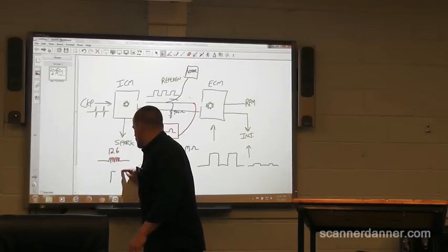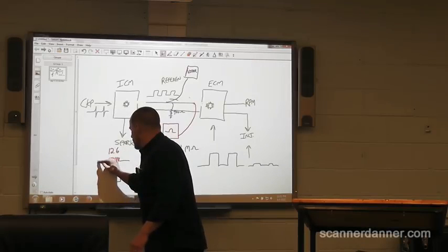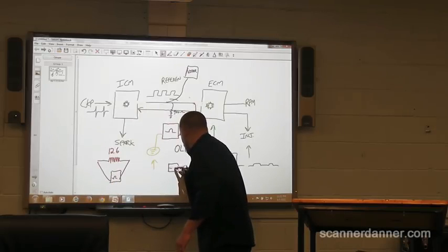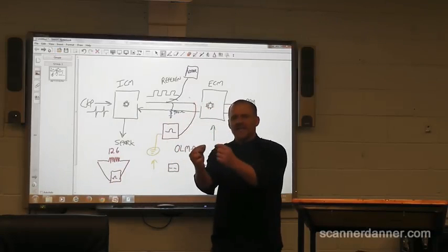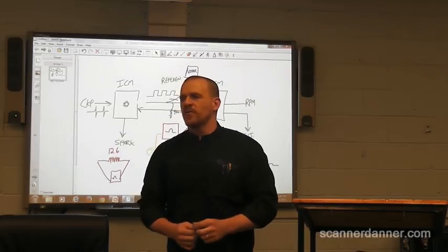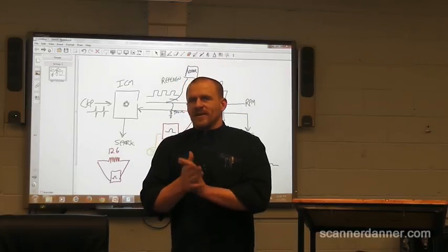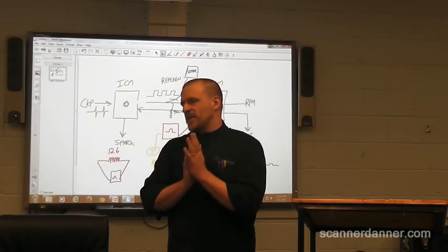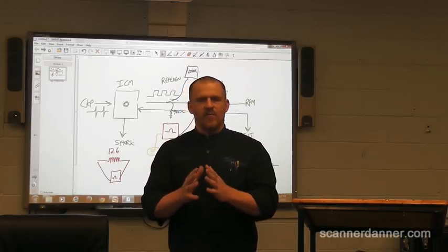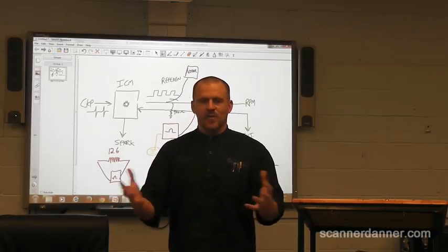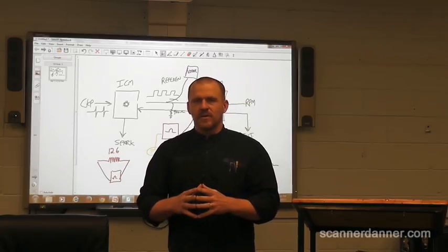If I'm measuring this particular fuel injector, I almost have to hold my leads on those terminals, because of how the top of the injector looks. Is that going to interfere with your reading? Mathematically, yes, but it's so small that it doesn't change the number. It still would read 12.6 regardless of your body having, say, 400,000 ohms.